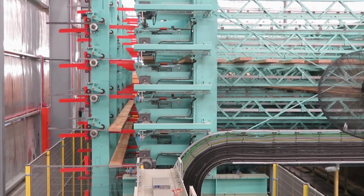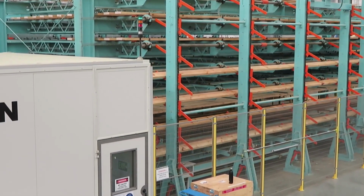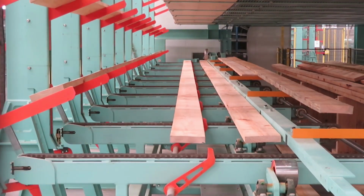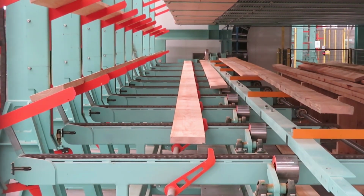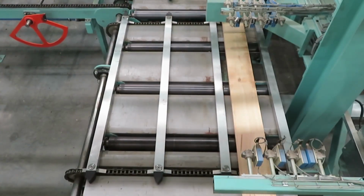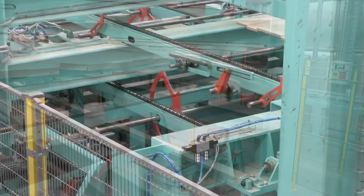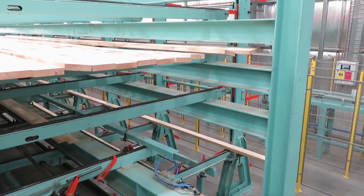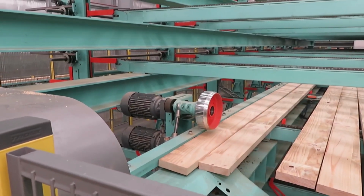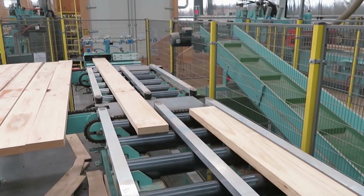Some will become long boards for the length of the billet, and some will become the cross boards, which is for the transverse lamella. It goes through the system until it has enough curing time for that glue, and then it will go into a planing, almost like a finishing type room, to make sure that the dimensional depth and width is appropriate for the type of billet. So any variability in the boards effectively gets planed out and they get machined down to the right size. Once they're machined, they get cut into lengths that are required for both that longitudinal and transverse.